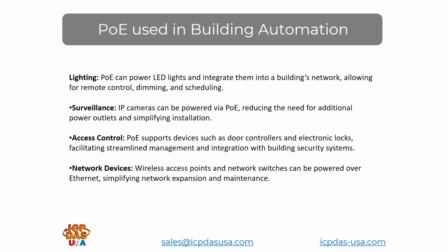For access control, you can use card or fingerprint type identification to control building access and improve security in the system. Also, you can implement it with standard devices. Anything Ethernet can also be incorporated with the PoE environment. You just need to supply power to the PoE-enabled equipment using special switches, but otherwise you can share the communication and everything to the standard or existing Ethernet network.